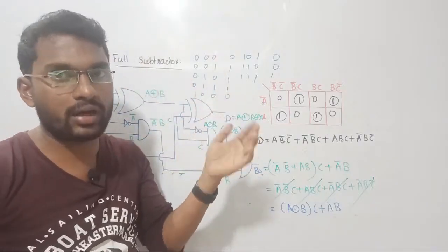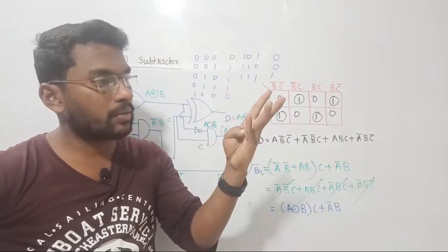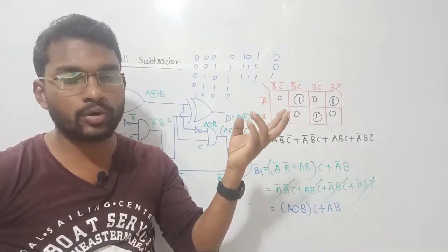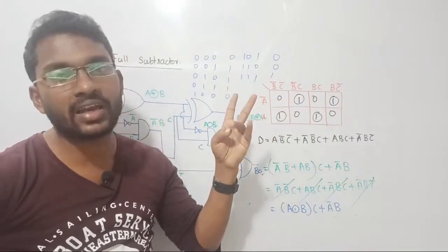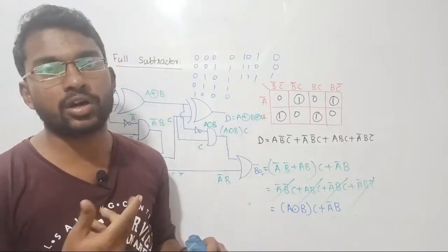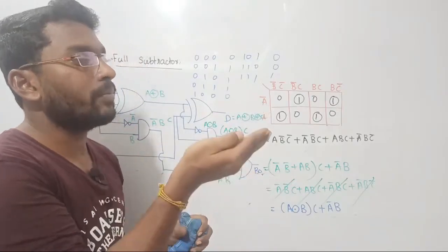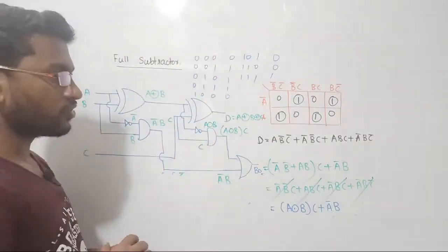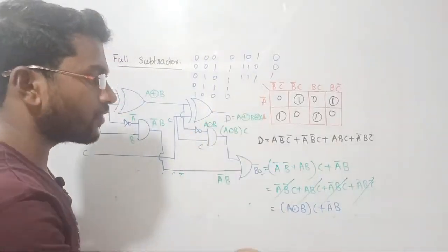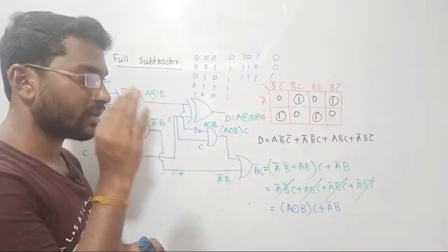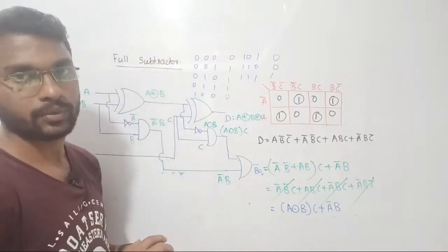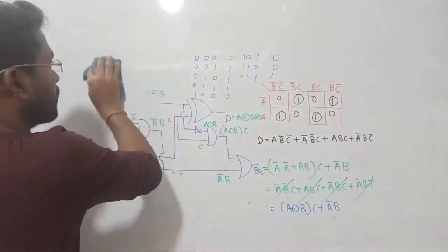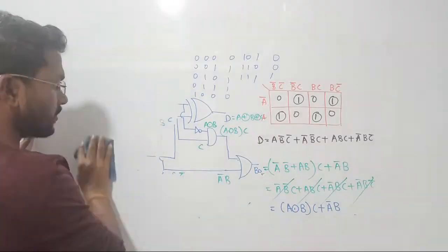If you take the full adder circuit, we are getting two outputs, one is sum, another one is carry, right? Are we considering both of them? No, we are not considering both of them. We are segregating them. In the sense, the carry generated while performing the addition should be added with the next MSB. But we are not adding like that in the case of the full adder circuit. So in order to complete the operation, the carry has to be added to the next bit. If carry is generated, then immediately that carry should be added with the next MSB bit while traveling from the LSB. So in order to perform that, the full adder will be extended as a parallel adder, right?